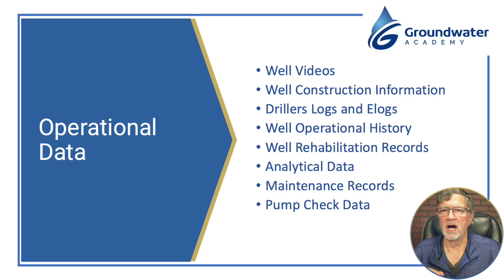This can all help us diagnose specific problems that you see from the chemical and the biological parameters, what's going on with the well. For instance, driller's logs are one of the first places I go. You can usually identify if you have a seal problem, a well construction problem. We've solved many problems just by looking at the driller's log and seeing what the problem was, and we were able to figure out how to fix it just from doing that. So that's going to be your friend. Don't pass this data by. You want to look at it.